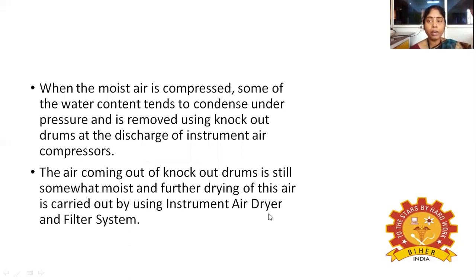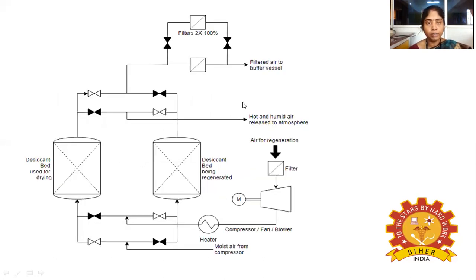If we give air with moisture, it causes contamination, so it has to be sterilized with the help of an air dryer and the filter system. This is the thing that helps give a detailed description of how the air is filtered and made sterile for any fermentation process.